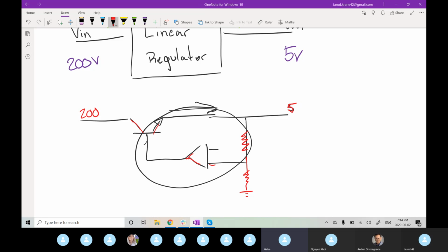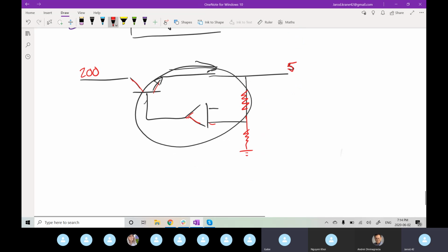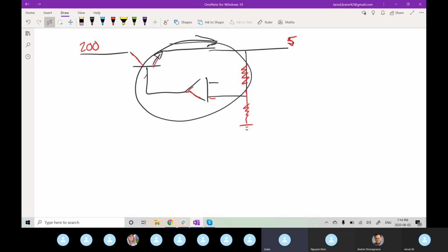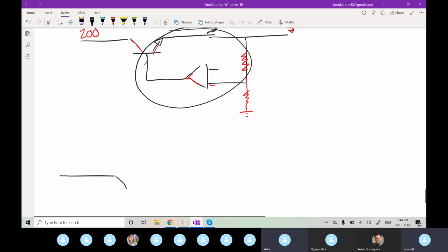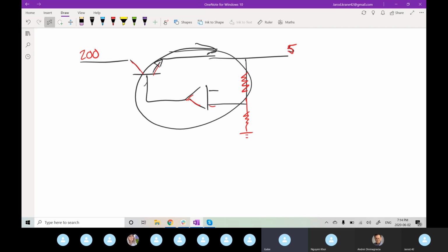Yeah. So for a linear regulator, between a DC-DC and a linear regulator, they're both going to have those feedback resistors and comparison networks. But where the real power gets dropped is across that transistor, right? So in a linear regulator, the golden rule is current in equals current out. So if you have 5 amps coming into the input, then that passes through the transistor and you have 5 amps coming out of it as well in that main current path.